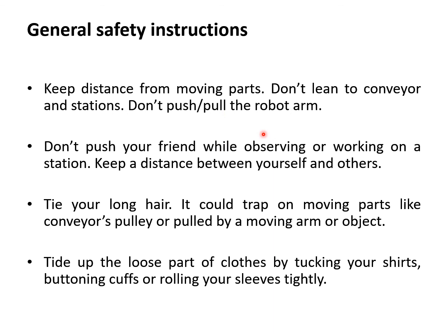Don't pull the robot arm. As I said, industrial robots are usually placed in a safety cage, so you cannot have access. So don't try to sneak in and touch the robot. If you are not authorized to enter that cage, don't go.